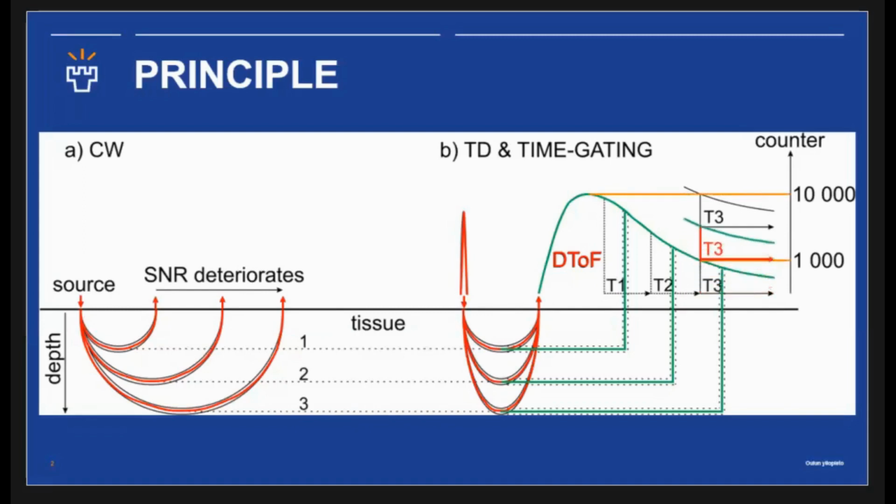Furthermore, the time gating increases the SNR and expands the dynamic range of the measurement because it allows the time window adjustment in relation to the laser pulse, and with that the early photons of the diode don't saturate the result.